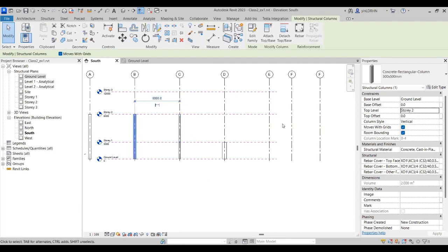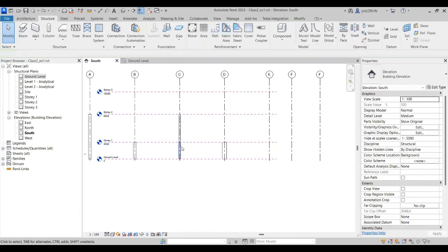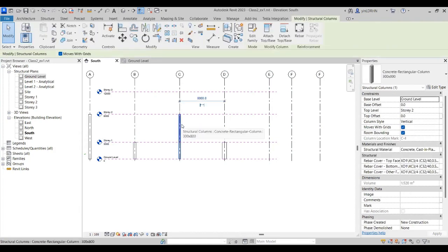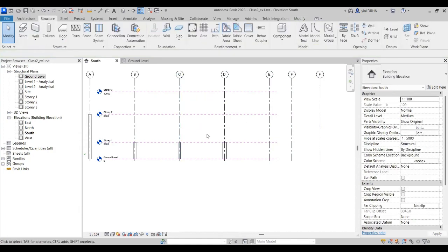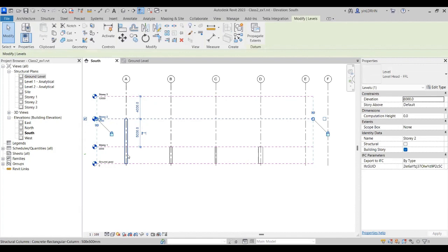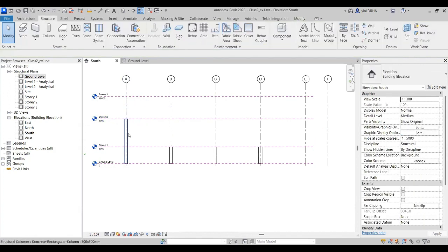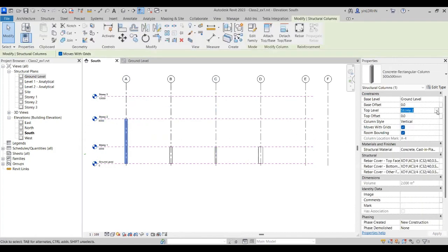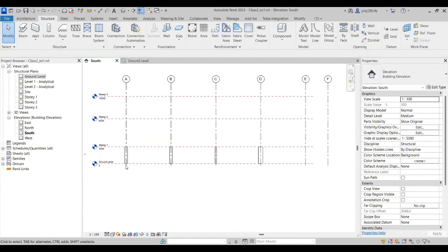That's why I say you have to keep in mind it is a wireframe, and how this wireframe works by columns like this. Understand? You have to think about the wireframe. If it runs through columns, some software gives a problem. Some software can understand, but some software makes wrong assumptions, so it doesn't divide your column at the intermediate level, and your beam may not connect properly.